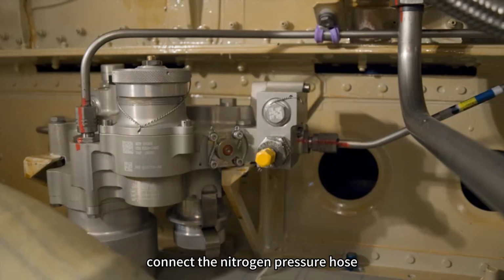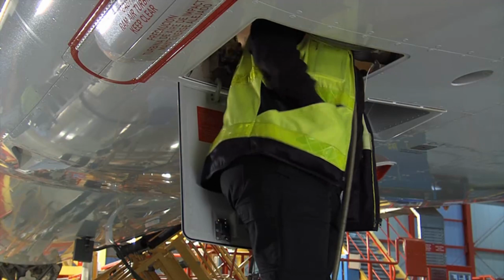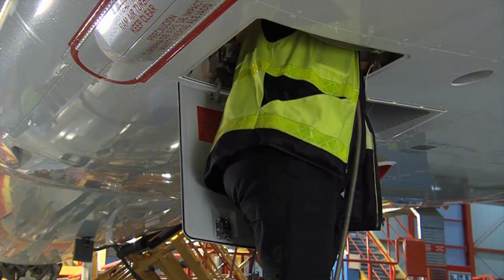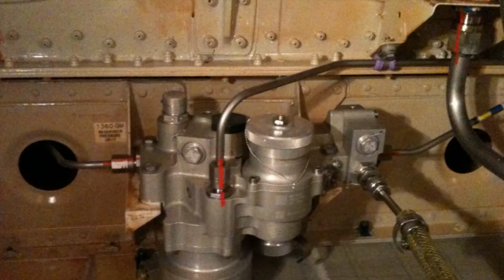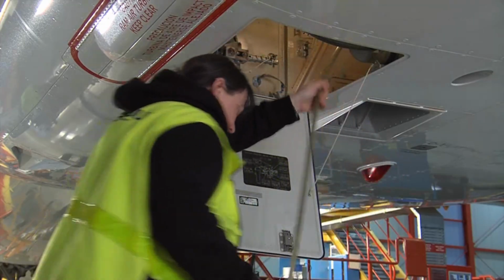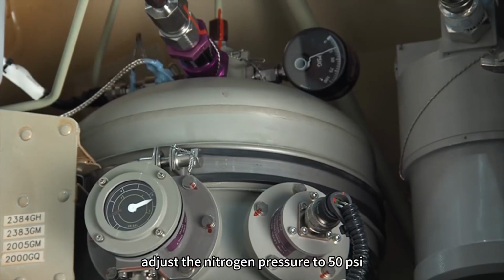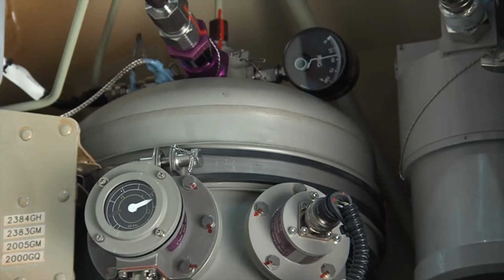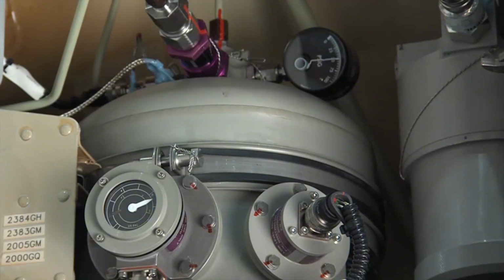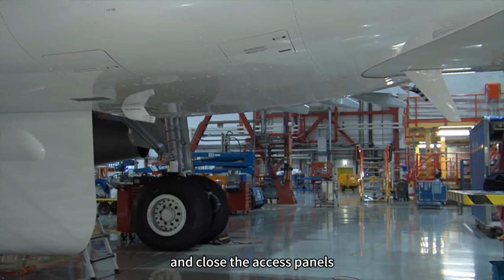Connect the nitrogen pressure hose to the air pressure manifold. Adjust the nitrogen pressure to 50 psi according to the pressure gauge on the reservoir. Disconnect the pressure hose and close the access panels.